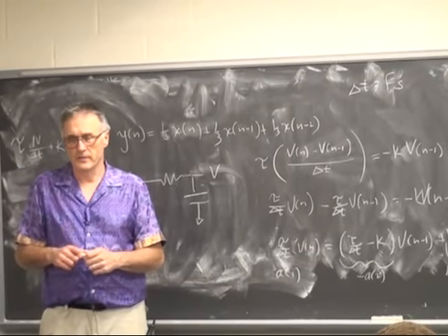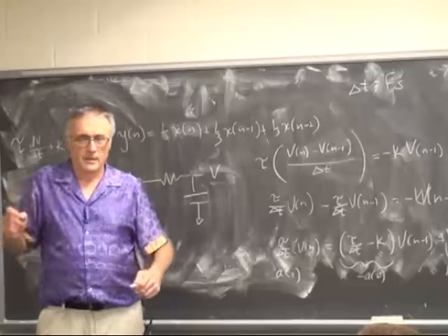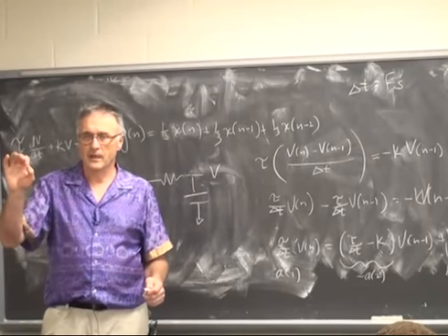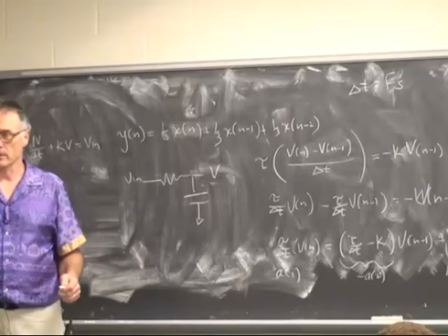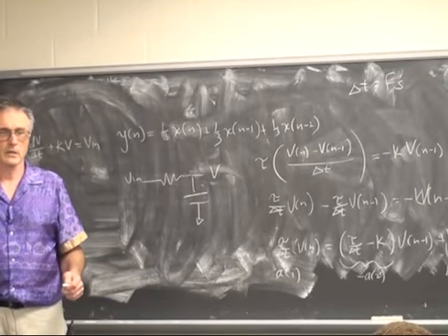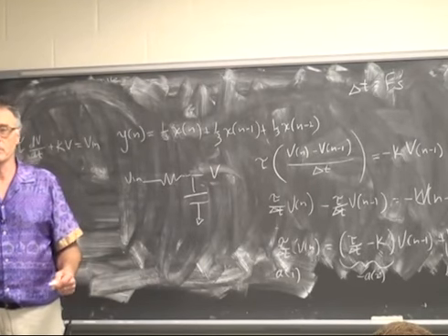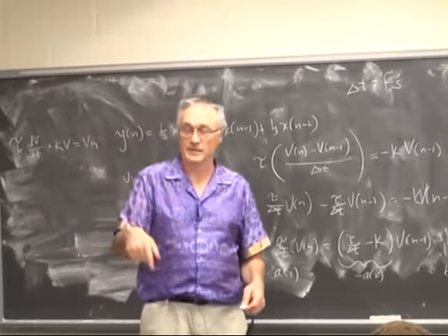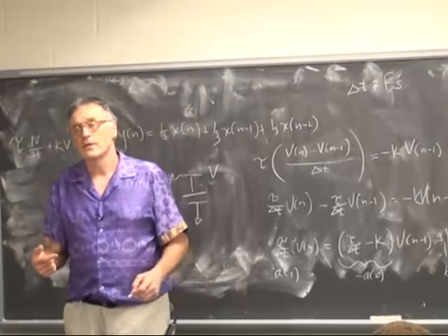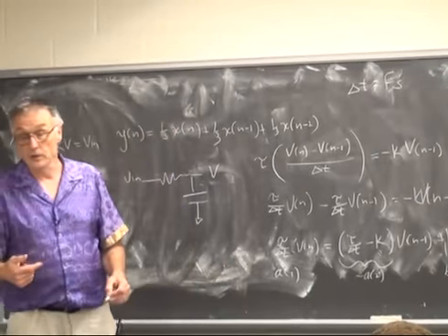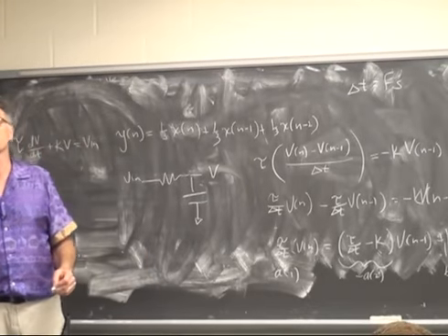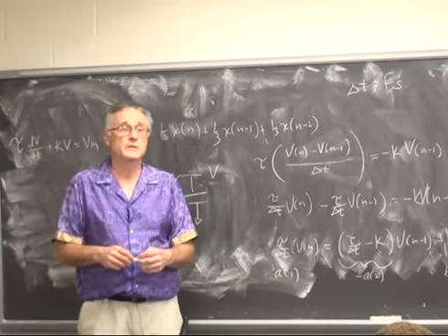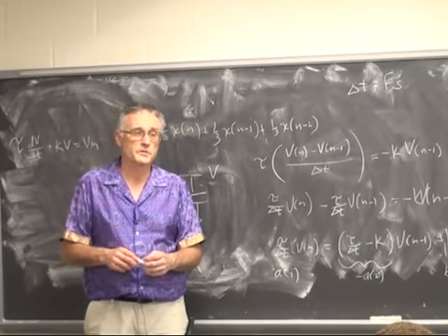The interesting part of this is the interfacing to the audio codec and the synchronization of the calculation with the audio codec, because you don't want the CPUs to run at full speed calculating as fast as they can, because you'll find that the CPUs run a good deal faster than is necessary for this application. You only want to do one calculation per sample.